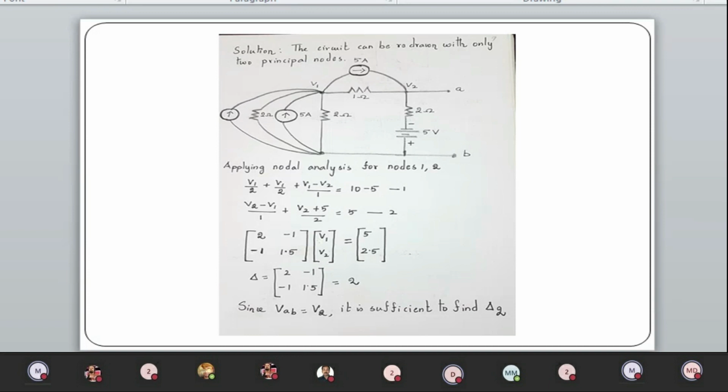Okay. So you have to open circuit the current source, and that is you have to deactivate both the current and the voltage source. Okay. So open circuit the current source and short circuit the voltage source. That is, you just draw a straight line with the 2 ohm, and you can remove the entire voltage sources.